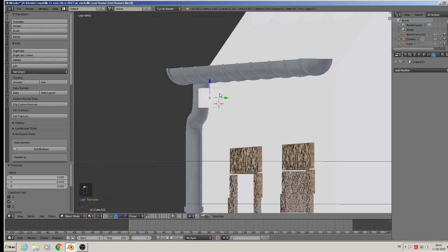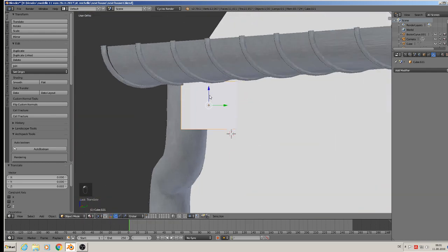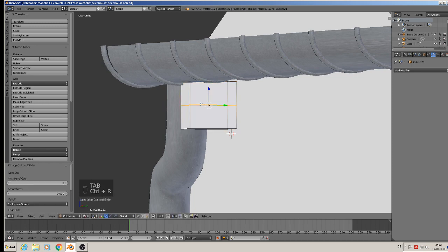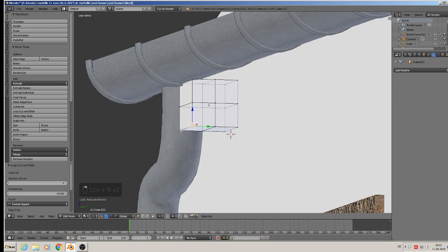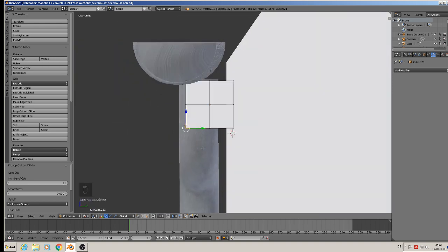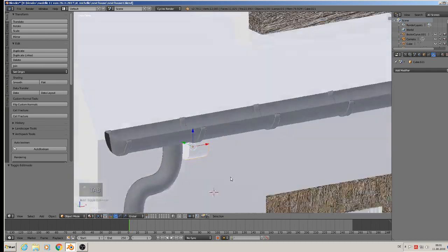And then we make it round at only one side. So make a middle loop and another loop, and then we get here this edge. Control B, move the mouse, roll the mouse wheel, and we have that round stuff there, and that's enough.